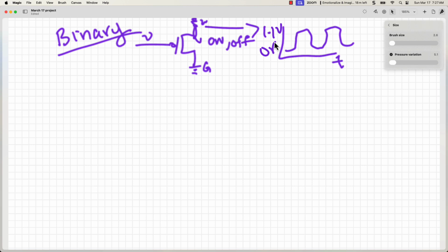Now, these levels you're going to see in DDR3 RAM. In CPUs, they could be lower, higher. And in DDR4, you're looking at 0.9 volts, I think it is. Don't quote me on that. This is actually a voltage, but for code purposes, we need some way to encode that. We can't look at voltages all day as programmers and developers and say, oh, we totally understand what's going on here. So we say it can only turn on or off. We'll call that a 0 if it's low enough, and we'll call it a 1 if it's high enough.